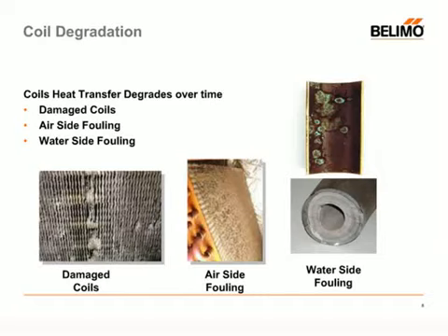Oversized valves, for example. When an engineer specifies a valve that has a specific CV, when a controls contractor goes to purchase that valve, the exact CV is not available. So do they buy a smaller valve? No, they typically buy a larger valve. So valves are inherently oversized from the get-go.